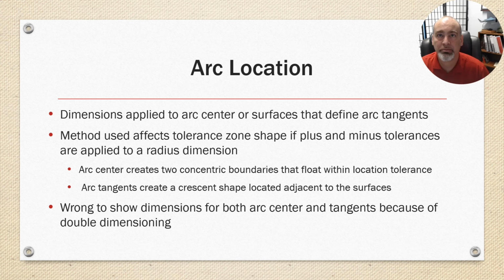It's wrong to show dimensions for both arc center and tangents because it would be over-constraining or over-defining the feature.